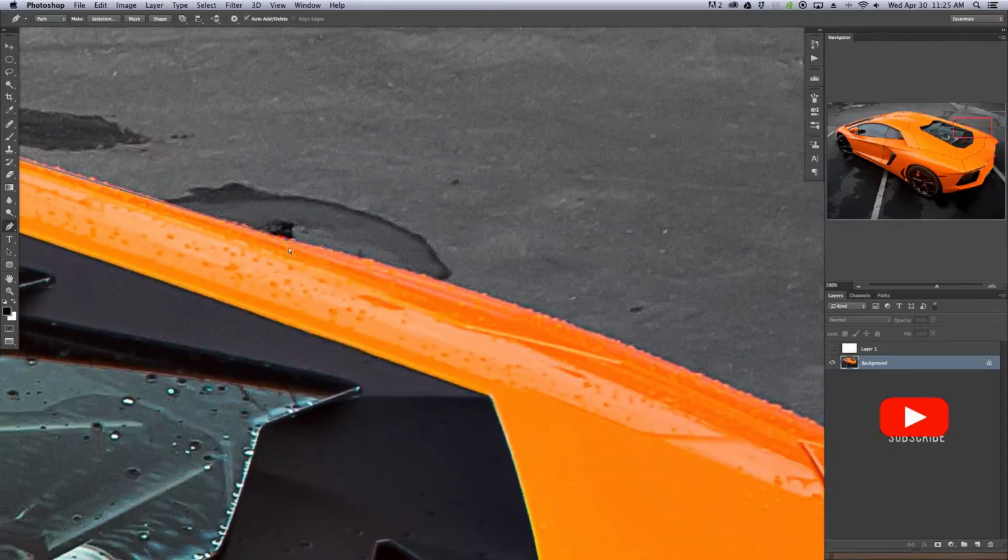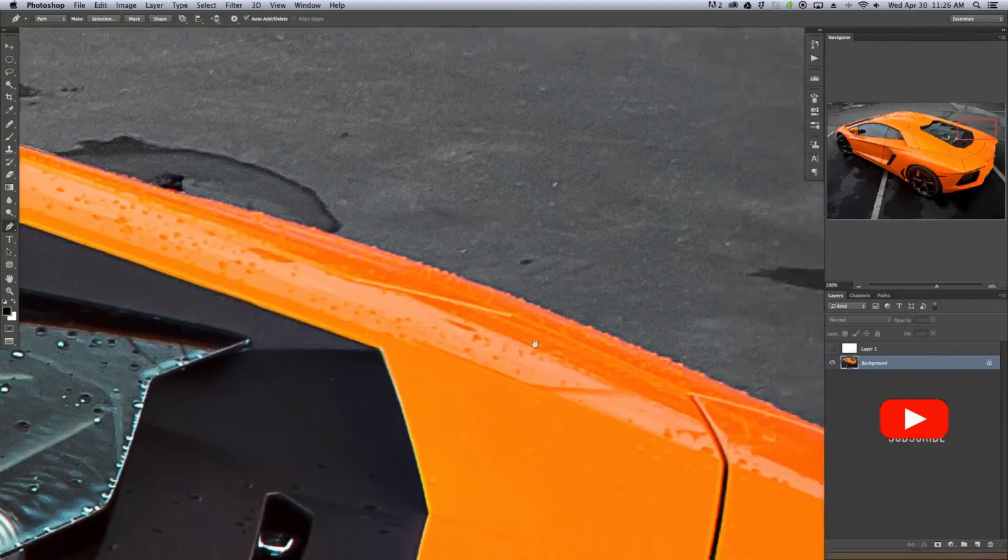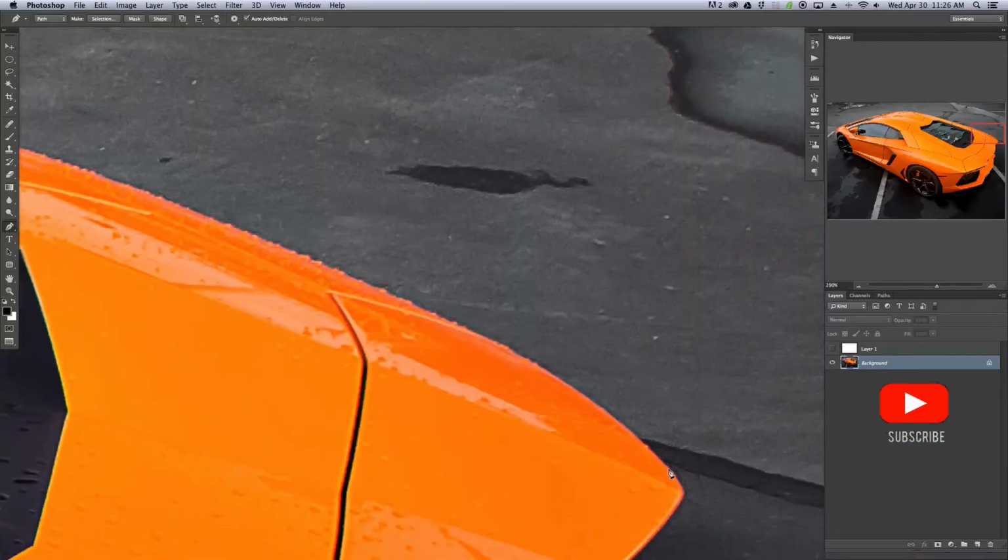So what I need to do is go to my old path. I'm going to find where my old path ended and hover over it, and we'll see a little square with two little sides sticking out of it. And that's basically the icon for continue along the same path. So we're going to click on that path, and now as I create another path, it's going to make sure we continue along that same path. So I'm going to click right about here. Again, hold Control or Command.